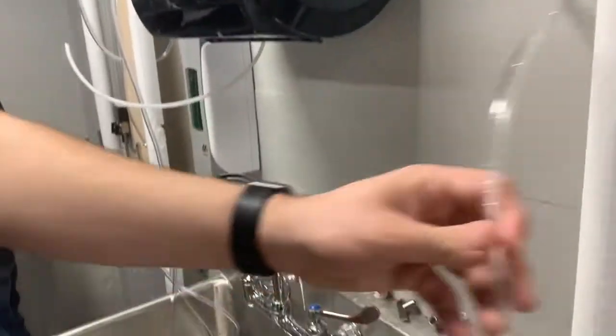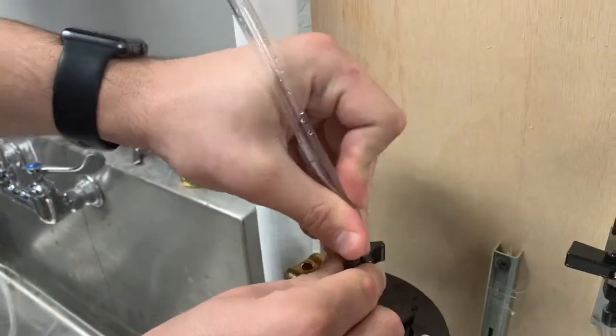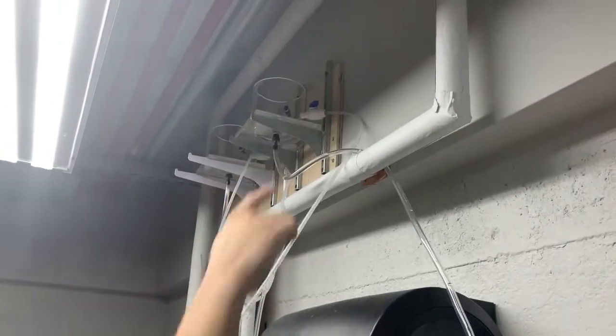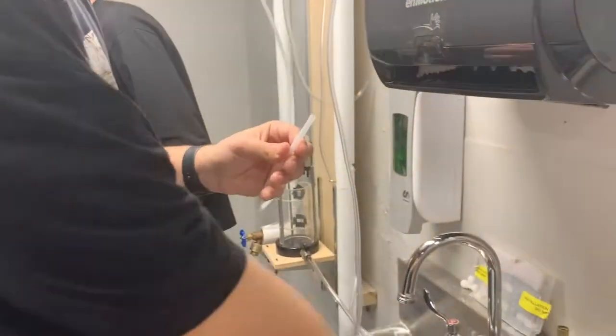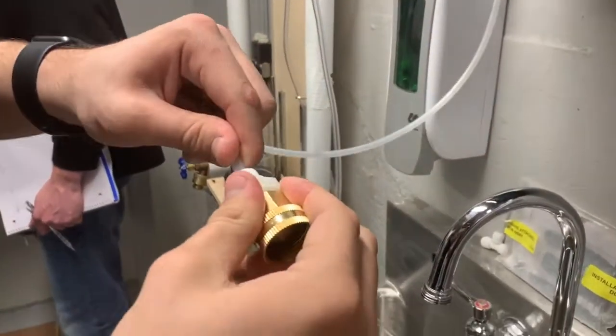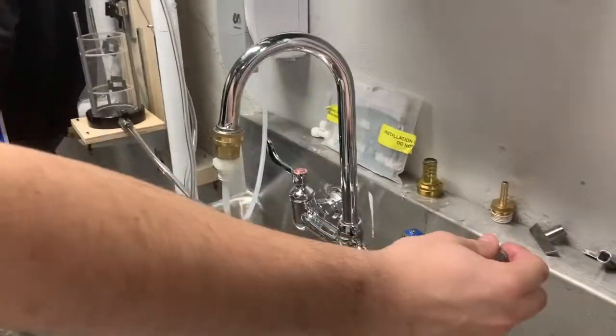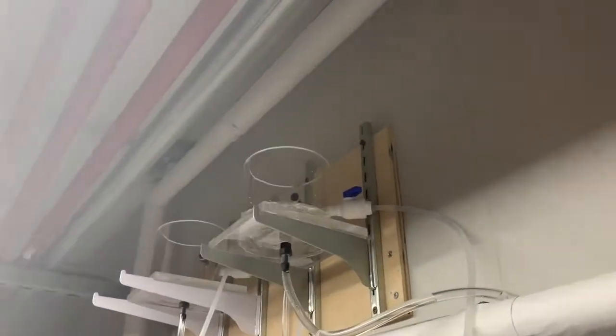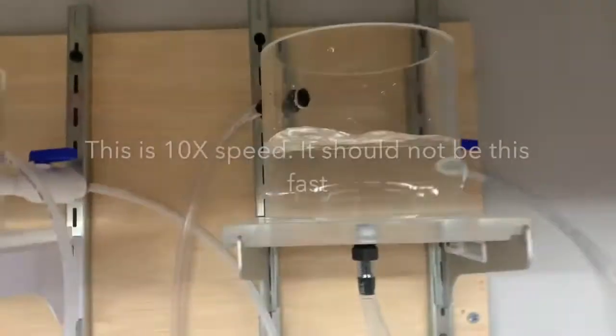Connect the tube from the head tank to the top of the apparatus. Connect the inlet of the head tank to the head of the sink. Turn the sink on. You don't need to turn it that much to get a good flow. Do not let the head tank overfill.